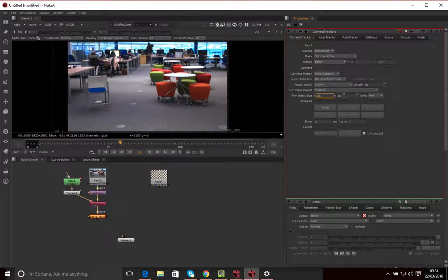If I decrease this, it will basically be as if, by making this smaller, I was making the focal length longer. It's narrowing the field of view. Okay. The important part is that both of these elements define our field of view, and what we need to do is know what the field of view of the camera is in order to be able to accurately solve the camera.